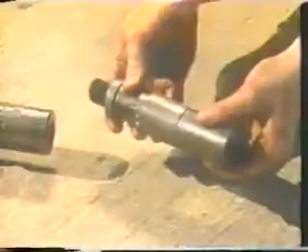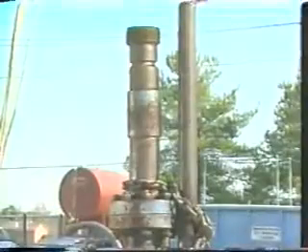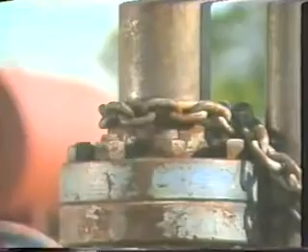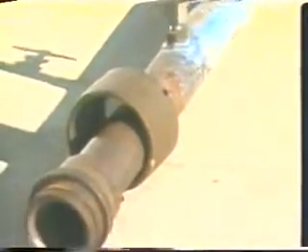When a wireline crew and the wireline equipment arrive at a well location to perform wireline service, there will be numerous pieces of equipment that must be assembled before wireline operations begin. First, the connection on the wellhead must be adapted to the connections used on the wireline equipment. The lubricator sections are laid out and assembled next to the wellhead. The lubricator is the sectional pipe used to contain the tools during entry and exit into the tubing.